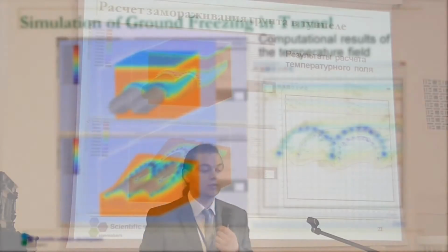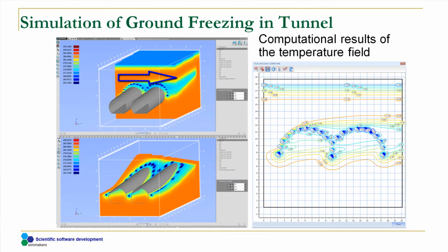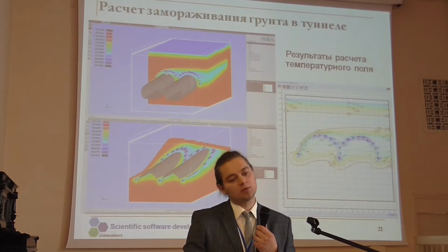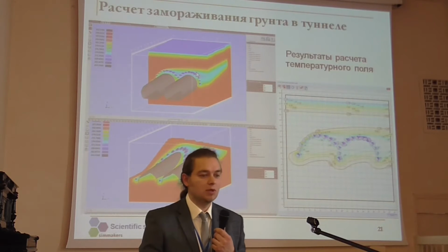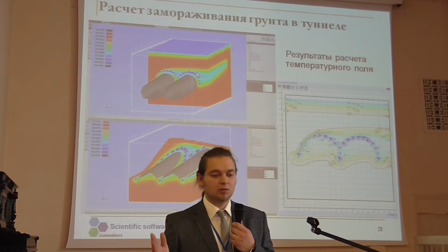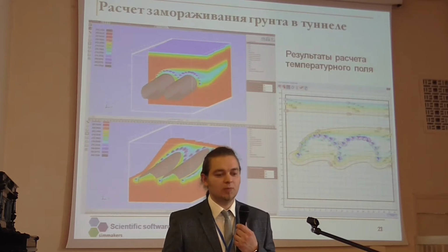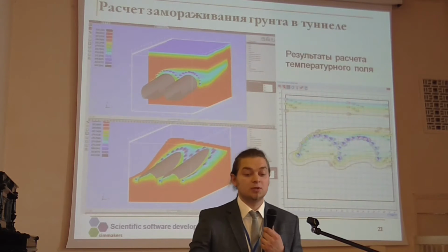It can be seen from this section how groundwater flowed in this direction. Tunnel number 1 became frozen, and so too did the second one, 1 month later. So, on the basis of computer modeling, construction engineers knew that they could start drilling the first tunnel after 2 months of freezing, and the second tunnel would be ready for drilling by the time the first was completed.